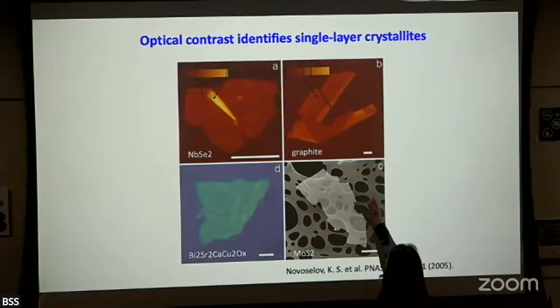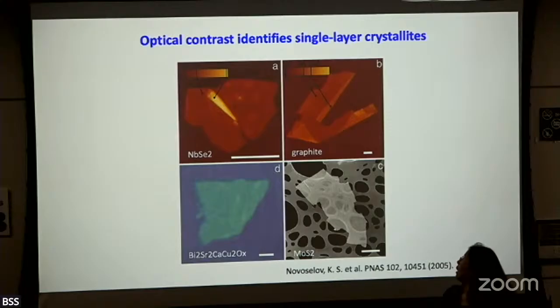So this is a substrate, and it has kind of an interesting color. Silicon has a band gap smaller than visible light energy. It should look black, but this has color. And the reason is because you have this thin oxide layer, and this is due to the interference effect. It's like oil on water. You see this kind of color. And this helps to see those layers, okay?